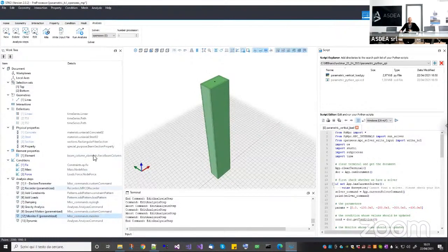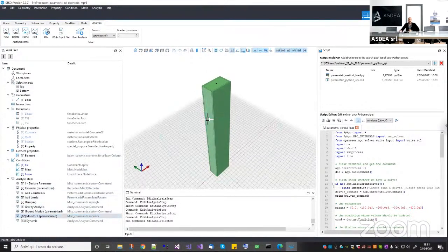So once you have done this, you can run the analysis, but you cannot run the analysis from here, because here if you put OpenSeesMP, you cannot set up the number of processors, because OpenSeesMP in STKO is meant to be used for parallel analysis of large models, okay? So you have to take one large model, partition it, but that is not a parametric analysis, okay? But you don't have to worry about this, because you can simply write the input file, like this.